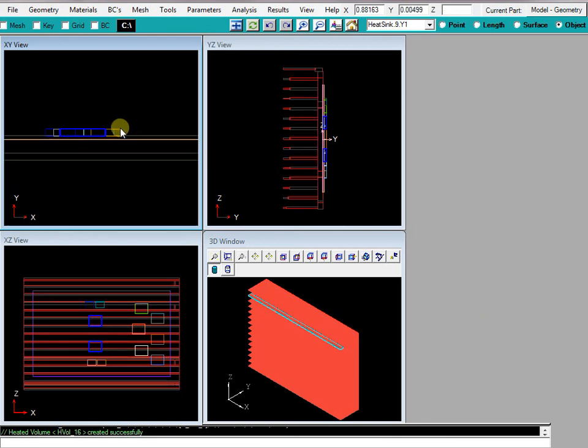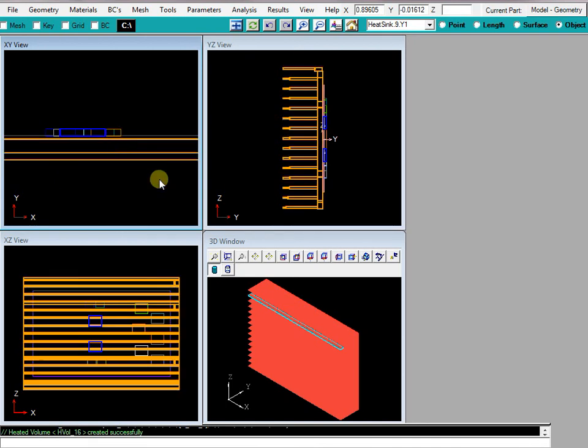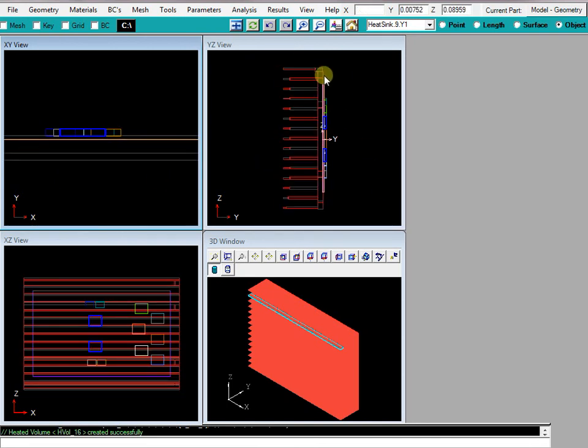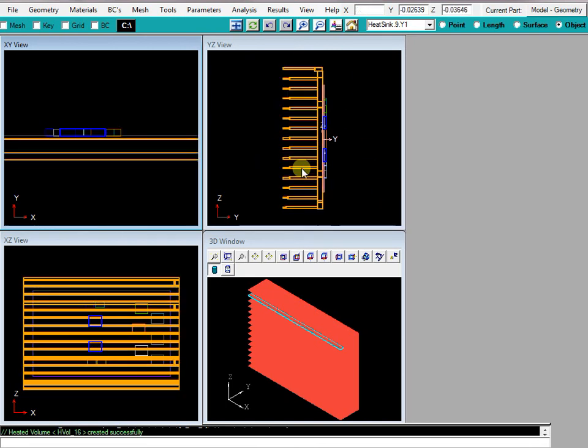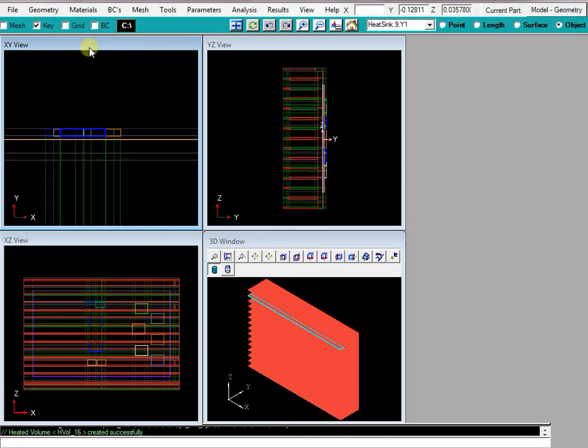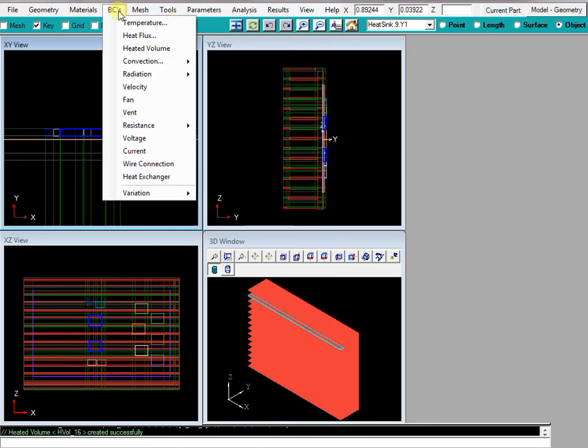And the next thing that we need to do is worry about the CFD. So how the model is actually going to be cooled is just going to be through CFD. At the moment, though, if we look at our mesh, it's right on the bounds, and there's no real place for the flow to grow. So we want to extend our plane.